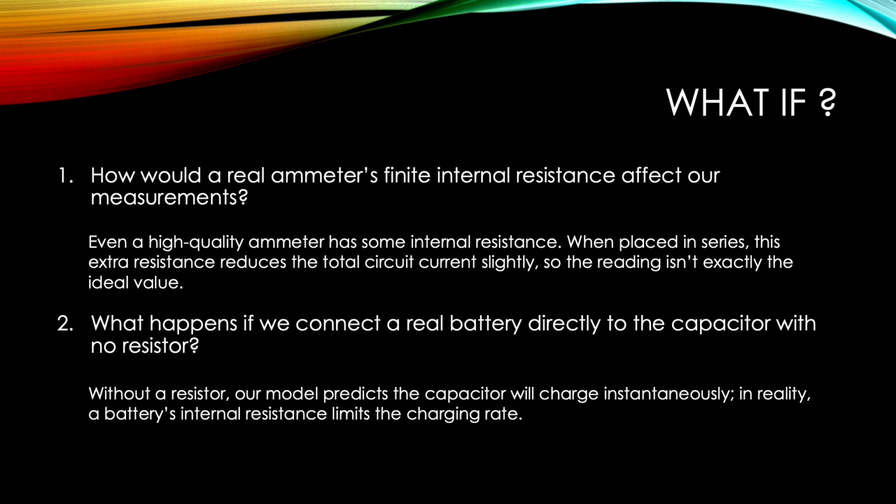What if? How would a real ammeter's finite internal resistance affect our measurements? Even a high quality ammeter has some internal resistance. When placed in series, this extra resistance reduces the total circuit's current slightly, so the reading isn't exactly the ideal value.